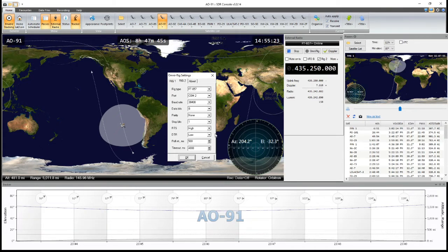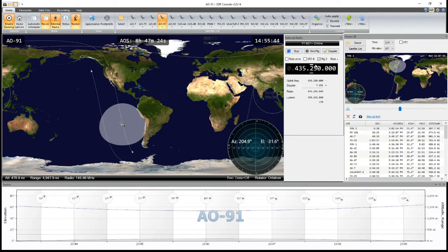Now, if you didn't start VSPE, it's not going to work. If you don't use VSPE and you're just doing a direct COM port connect, then yes, you can just put in COM11 here, remember, from the setup. I know, hopefully it's not too confusing. But anyways, so this is online. And if you have multiple rigs in there, you have to make sure OmniRig is looking at the correct rig. By default, it's probably going to look for rig 1 in OmniRig if you have 2 rigs. If the 857 is on rig 2, you need to make sure this is checked, and it will automatically start the radio.